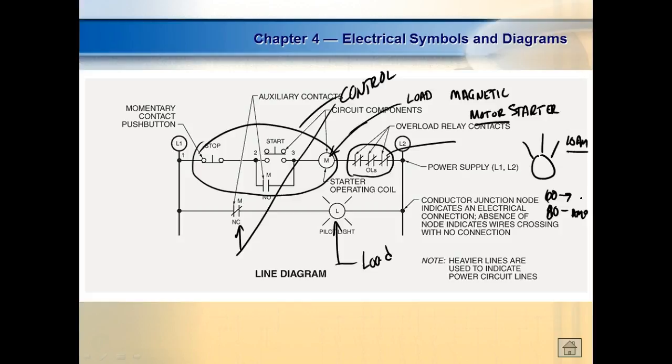Well, what would happen if the motor stalled? It'd burn up, because now it's going to try to pull starting current. If it stalls, it's going to try to start. You understand that? So it pulls starting current, and we don't have any protection for it, so it would burn up. So what we have to do on motors is have a secondary protection. We call them overloads.